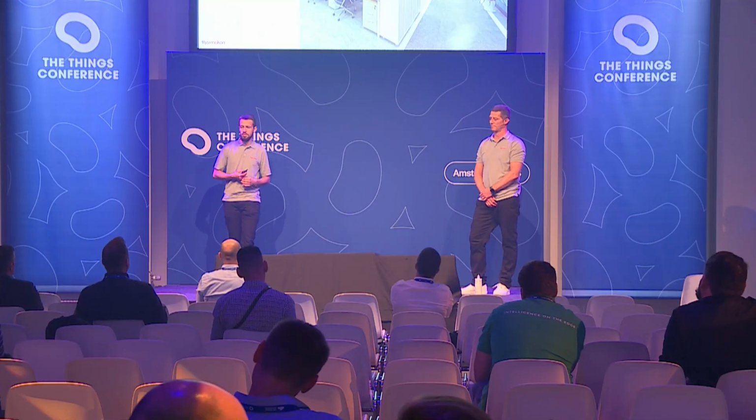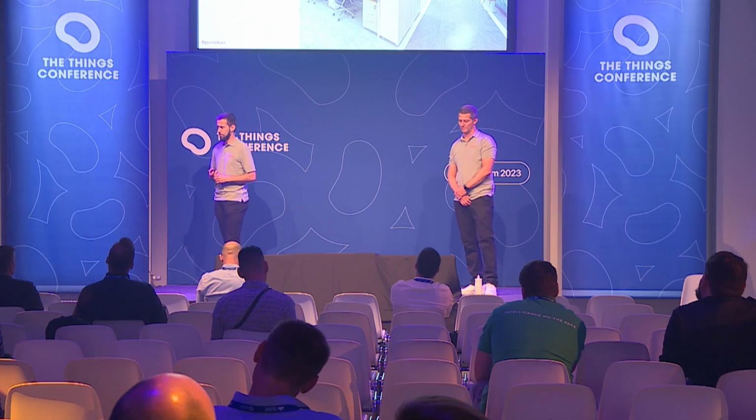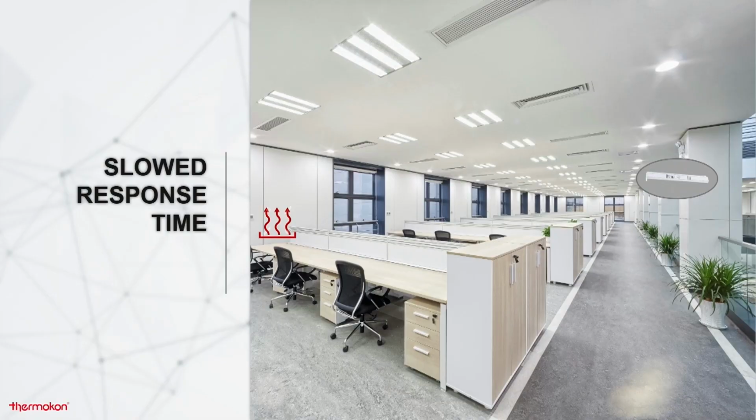Another point is a slowed response time. In offices, we sometimes have big open spaces with the heat source on the left-hand side or very far in the back, and just one temperature sensor mounted to gather the temperature value of the room. If there is a big distance between the two, the response time can also lead to a deviation that is later seen in the application. Now we want to see how we can combine all these points into one application and what this means for it.